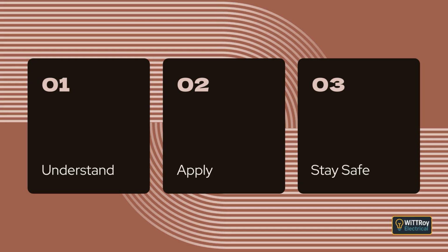Clause 2.5.7.2, Coordination of protective devices. Clause 2.5.7.2 introduces the idea of coordinating different protective devices. When we have more than one protective device on a circuit path, they must work in the correct order. This is often called discrimination or cascading. We want the device closest to the fault to trip first.